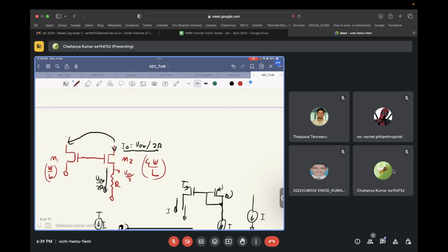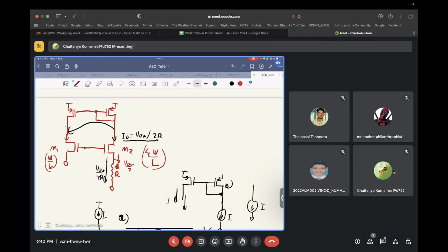So you will use a PMOS current mirror for that. Here the current is generated; this is the branch where the current is generated. Here you will have the diode connected PMOS, and the current that flows needs to be pushed into transistor M1. So in this case, you will have an open one. Now, in order to generate the VGS of this transistor, you will just short this thing like this. You understand the circuit?